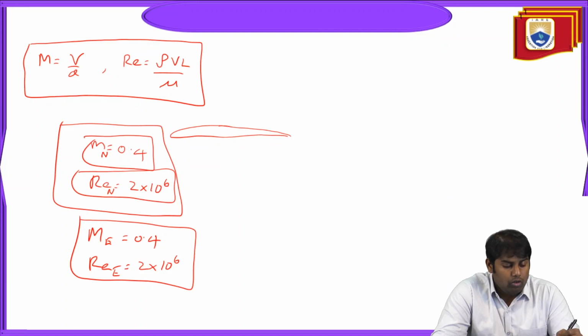But now, what we have additionally is the Mach number. We have seen what the different regimes of Mach number are and what its importance is. As you increase the Mach number, the Reynolds number independence will come, only Mach number dependency will come. Only Mach number dependency in the sense that for very, very high speed flows, or very, very high Mach numbers, only the Mach number is sufficient to compare the experimental and the numerical things.